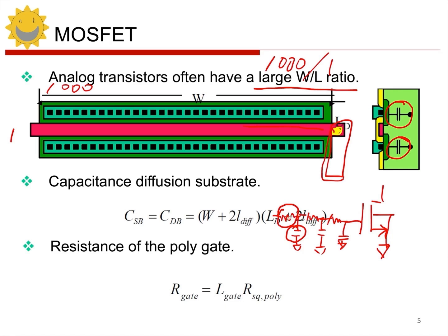If this resistance is large and the gate is particularly long, then this RC model will also be particularly long, right? Clearly, this will lead to what? If I apply a signal here, then when it actually reaches the real control terminal, which is the gate terminal, it will definitely cause distortion, right? There will definitely be distortion. If the signal frequency is particularly high, then it's very likely that the signal that truly controls the gate has already disappeared, right?